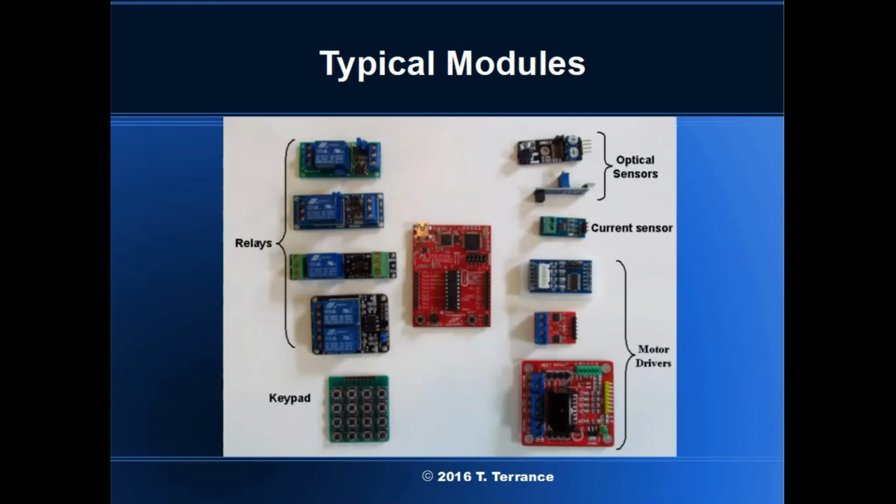Next up is a keypad. The keypad is an exception to the 3-wire interface rule. Most keypads are matrixed, that is there's an output pin for every row and every column. Your microcontroller must be configured for as many input pins. When a key is pressed, that row and that column will go low, and your microcontroller can interpret whatever letter, number or function assigned has been activated.